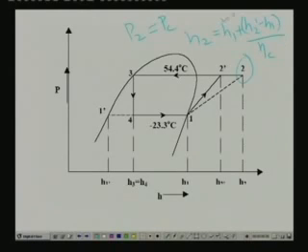H1 is known to us, H2 dash is known to us also, and the efficiency is given as input. So, we can also find out the enthalpy. So, for this point, use the pressure data and enthalpy data and find out the rest of the properties. Now, coming back to point 1 dash, point 1 dash is nothing but the saturated liquid at evaporator temperature.